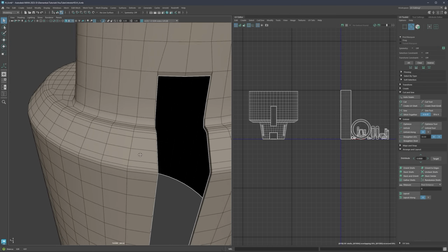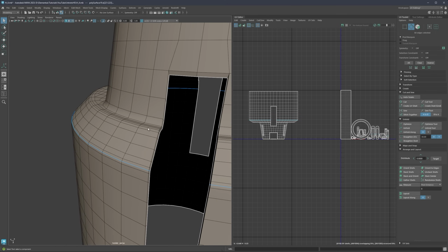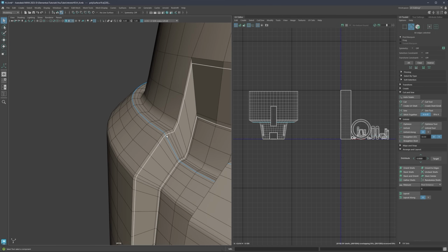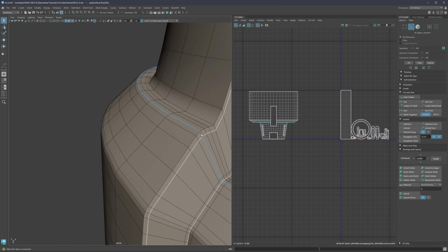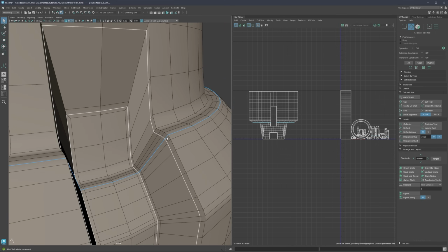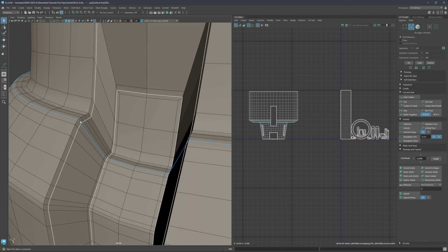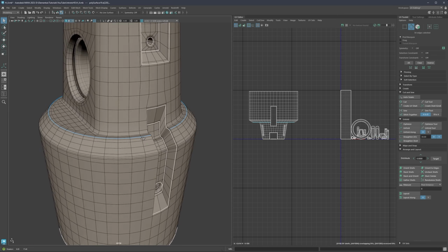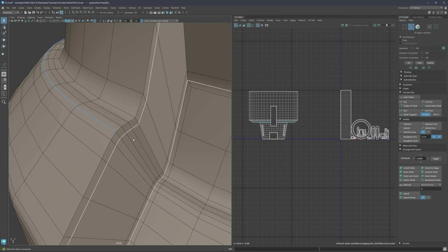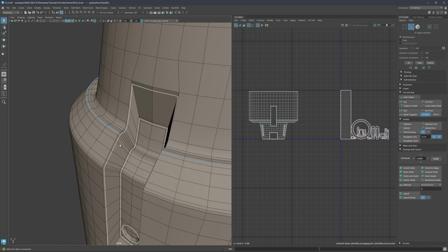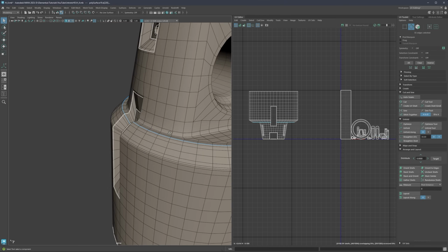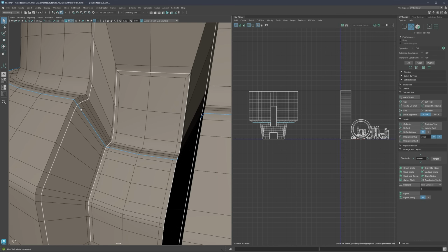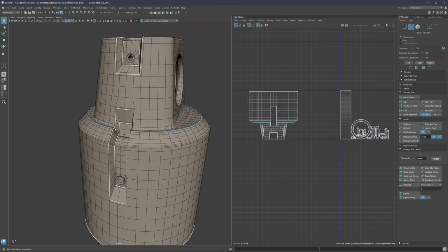And the same thing, let's now find a nice place for a seam, and it's going to be these two places. So the easiest is just going to be to create camera-based UVs here. So select the shell, create camera-based, push it to the side, and now we can easily from here select the cuts. So we don't have to worry selecting the whole loop. All right, so let's create a cut and then UV shell and then unfold, unfold.